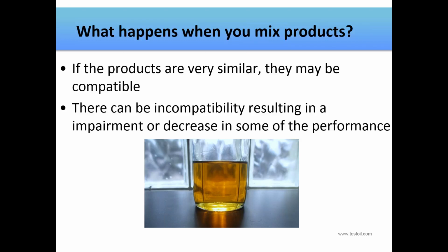The speed at which the incompatibility problems potentially develop over time can be provoked by several factors, and it can include, but is not limited to, the nature of the incompatibility, which may include incompatible base stocks or additives, or the presence of contaminants already in the system.